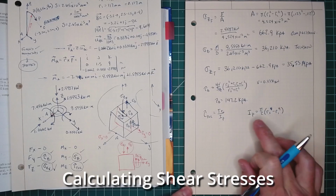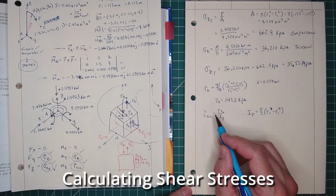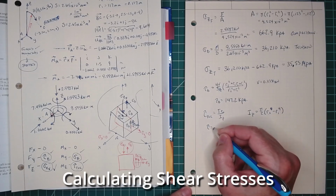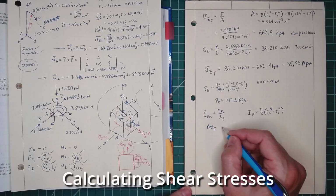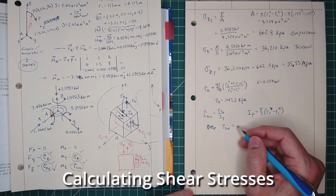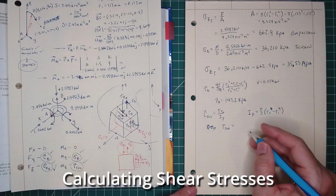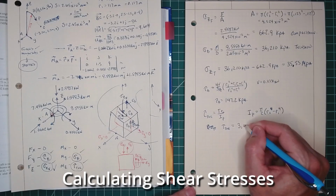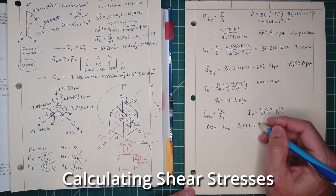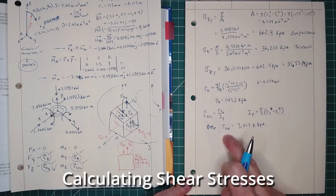So we can calculate IP, plug IP in here, plug R2 in, we know T, and we can then calculate our shear stress due to our torque. Plugging that all in, we get 3,017.8 kilopascals.